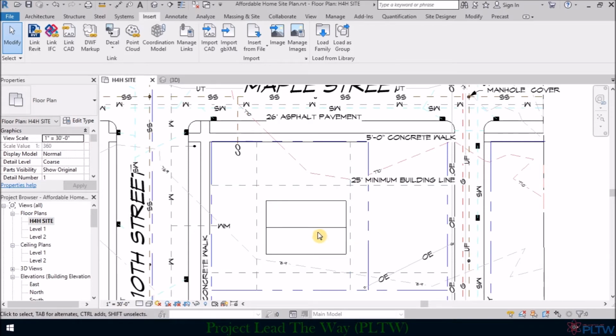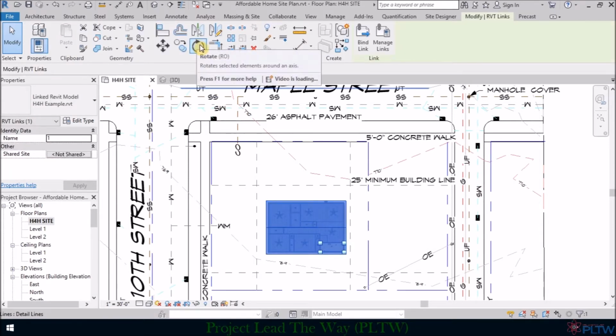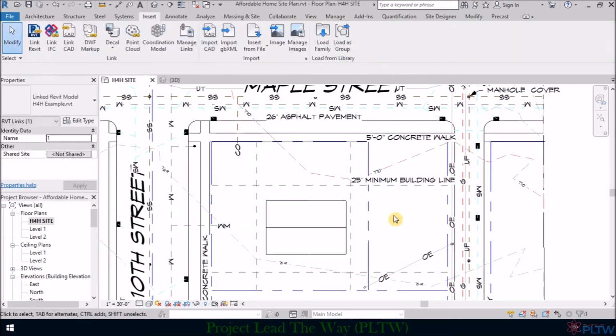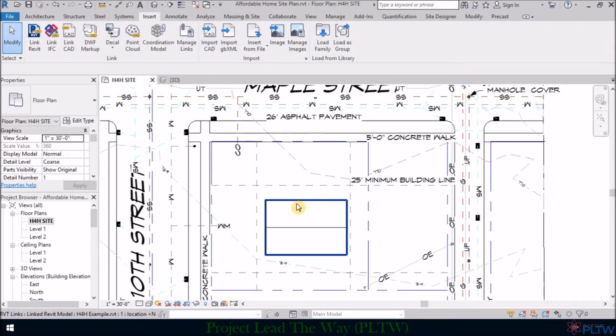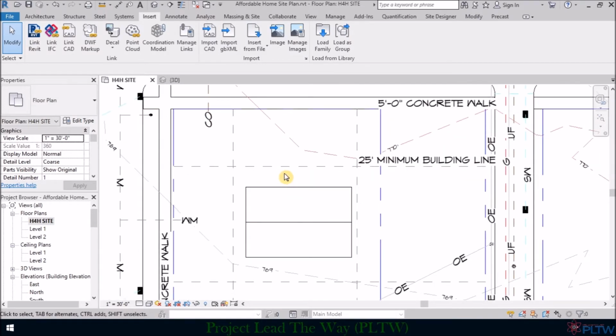180 degrees. To do that, you simply click on the structure and click on the rotate option, and it will find the center of the entire structure. All you need to do is click, as I'm about to do, at the 0 degree angle, and then drag this line over and make sure it says 180, and click again. I have just rotated the entire structure 180 degrees.